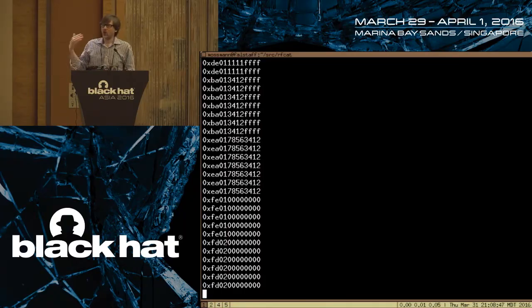It looks like it's just a simple addition or subtraction of all of these things. When I enter in all zeros and then a lock code, which is just 1, I set 1 bit, and you'll notice that the resulting checksum is FF minus 1. Then when I had a nibble that was 2, the checksum is FF minus 2. So it's probably just a subtraction of all of the bytes in a row.